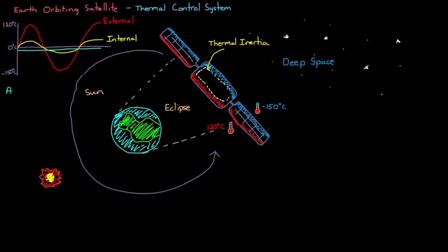Let's say for this example that we predicted the average internal temperature for our spacecraft to be around minus 5 degrees C. So what does that mean for us? Well, our spacecraft has batteries, and they like to operate between ranges like 0 to 20 degrees Celsius or so. It depends on the battery chemistry. So if it gets outside that range, the spacecraft and the entire mission could be in trouble. And our job is to develop a way to keep the batteries in this temperature range.